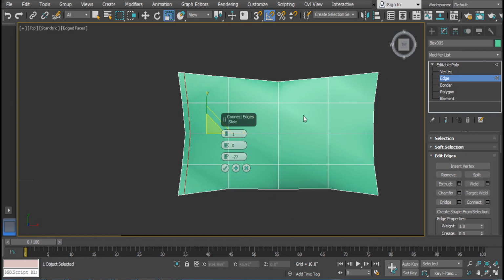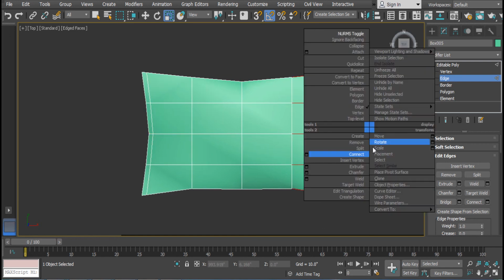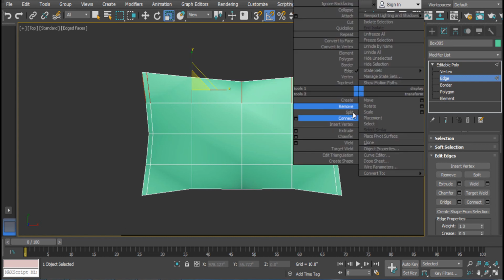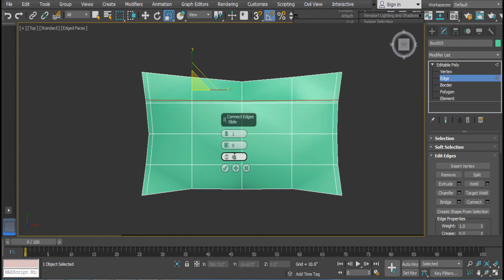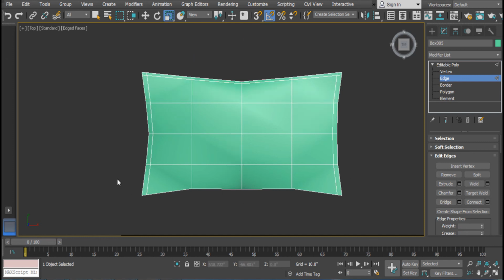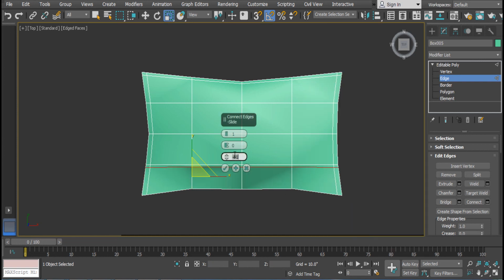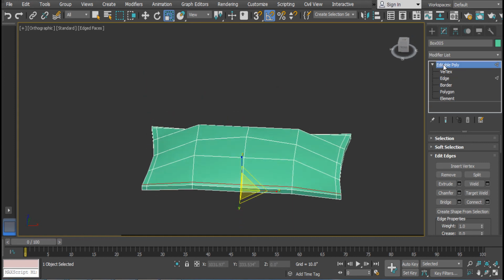So you need to scale that vertex. Right now we can check with the nurbs toggle, so you got the shape or not, but still not. Why? There are no edge lines. So you need to select the edge lines. You need to select those sharp lines; those lines are needed to get this smoother shape.